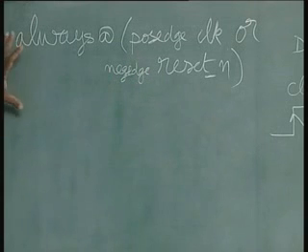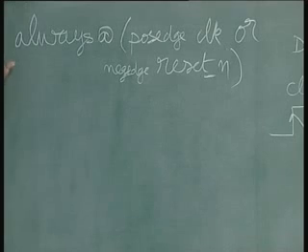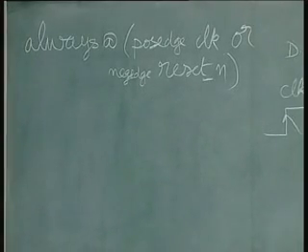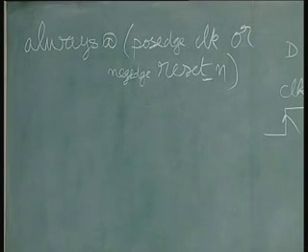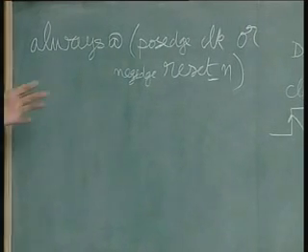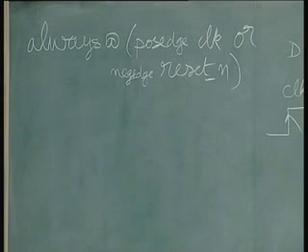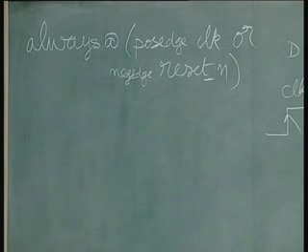Right? So in sequential realization, a flip-flop or register, another name usually encountered is a register instead of a flip-flop. Hereafter we may be referring to a register as such, which simply means either a D flip-flop or any other flip-flops. Fundamentally, when you see a synthesis tool and finally get the circuit out of it for the code that you have written, you will be seeing only D flip-flop in most of the places. In fact, almost all the places D flip-flop will be used.